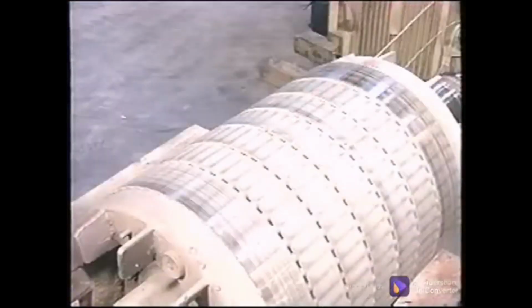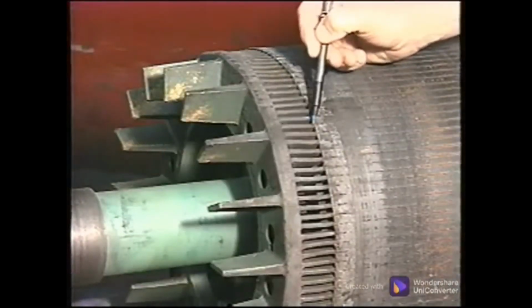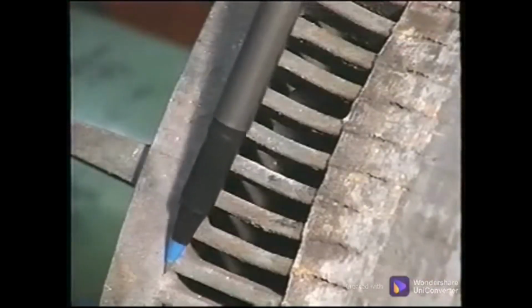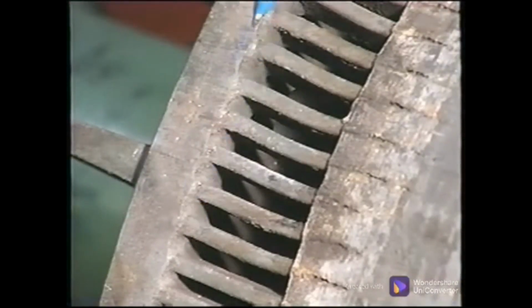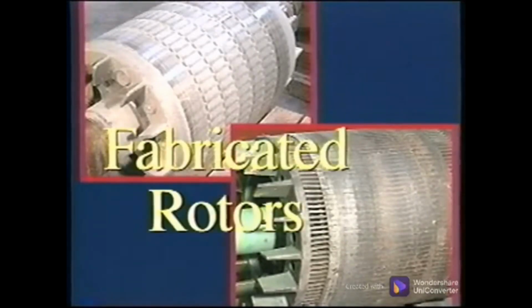The rotor itself is made up of rotor bars connected by end rings and a core. The core is made of individual soft iron laminations insulated from each other, which reduces the amount of eddy current traveling through the core and therefore reduces heat and increases efficiency. The end rings and bars can be cast onto the core as one piece using a material like aluminum, or they can be individual bars such as copper that are then connected to end rings. These bars and end rings carry the current and must have good connections. This type of rotor is usually referred to as a manufactured or fabricated rotor.